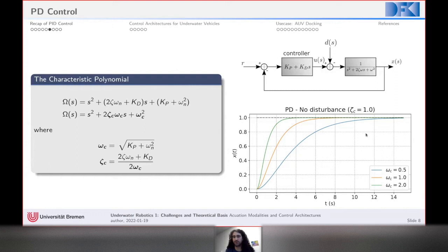And this is how you can observe that. Now, if you increase this a lot, you are driving the system to be a little bit unstable again, right? So here's how you can design your system by playing around with the frequency of the system and the damping, or the relative damping ratio of the system.